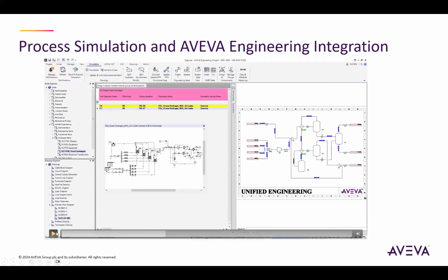He wants to go through what we refer to as the intelligent type of information passing, passing information from the process simulation graphical presentation into the BFD by simply dragging and dropping the information into the BFD, where information is automatically passed on for the same type of class, in this case the exchangers.